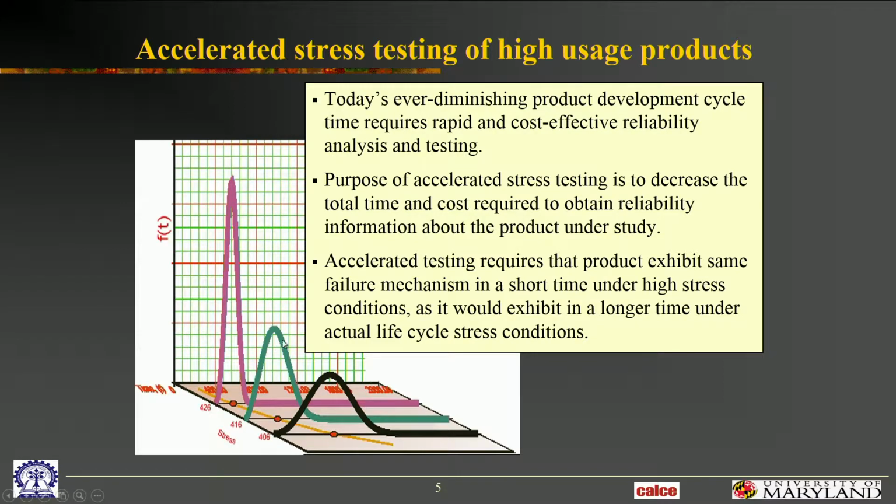The other thing I want to point out is these probability density functions are getting taller and narrower. That's something we do observe. As you get to higher and higher stress levels, we tend to find that for the same failure mechanism, same material, same defect density and everything, same variability, the failures tend to get more and more clustered. That means higher stress level narrows the distribution between the worst and the best components. And that's why it's getting taller, because remember, the area under the PDF is still 1, unity. So if the base gets narrow, then the distribution gets taller.